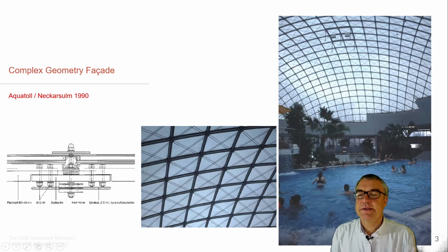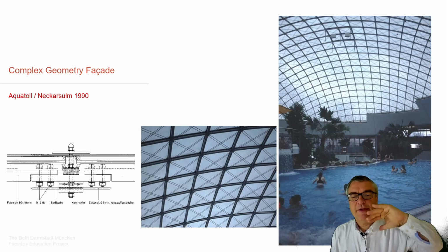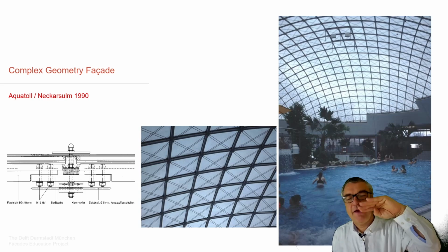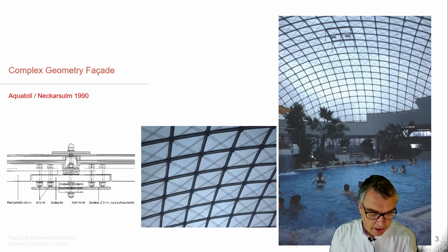What we see is this is the main structure, these steel bars here. Due to the very slender structure, this whole thing needs to be pre-stressed with a cable mesh. The cable mesh is what we see here. And then on top of it, glass plates, insulated glass units in this situation, which are actually straight and then have an iterating surface to create this freeform shell.